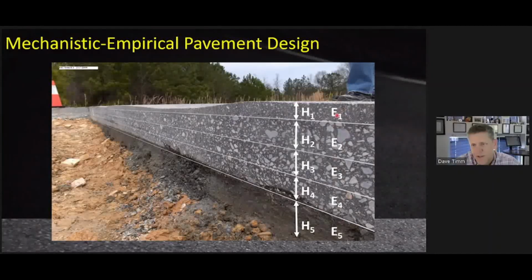So this would be like dynamic modulus of the AC layers, and we put in trial thicknesses. We simulate loading events on the pavement structure, and using computer models, we make a prediction about how much stress or strain this axle load or this wheel load causes at the bottom as a predictor for cracking to propagate to the top, knowing all the properties over here.